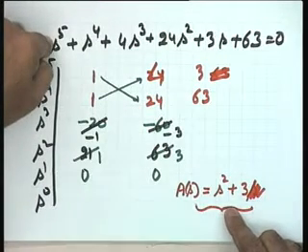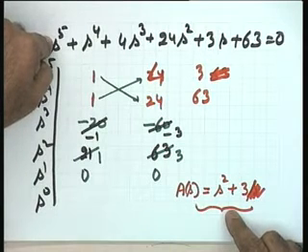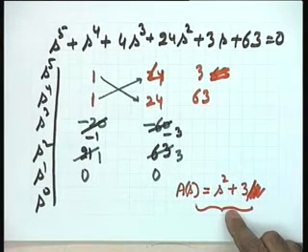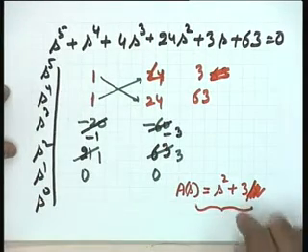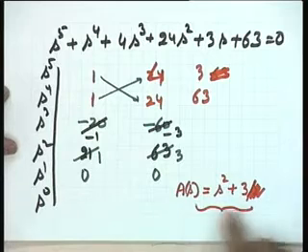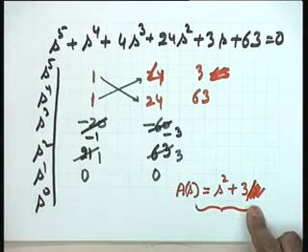Is it sufficient to conclude in this example that the system is marginally stable? Probably not, because we have not said anything regarding the remaining roots. The only thing it says is that the two roots given by this particular auxiliary equation are on the imaginary axis, but the remaining roots you have yet to examine. And how to examine the remaining roots?